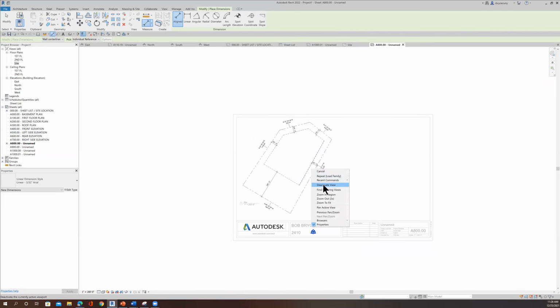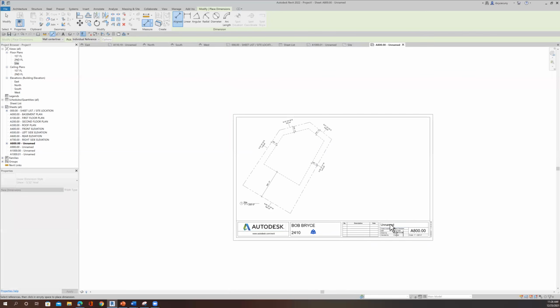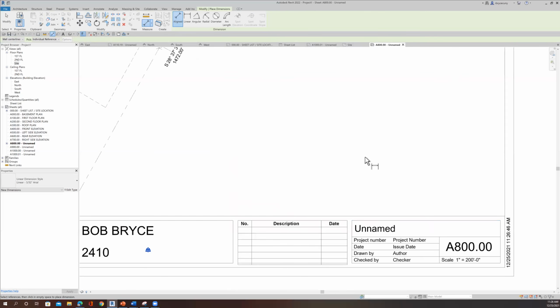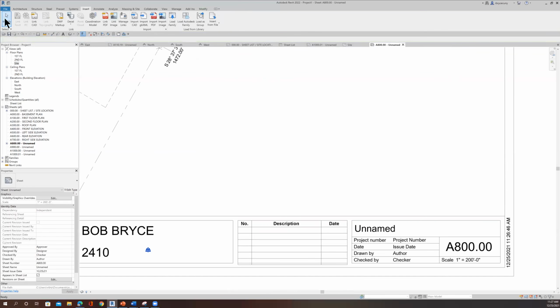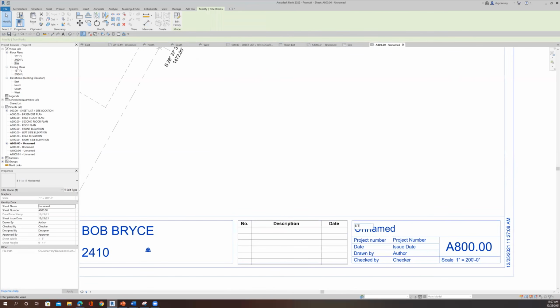So right click, deactivate the view. Let's call it, we'll rename it right here. Let's get in here and rename it. Click on it. Whoops, see that little icon next to my mouse cursor. You can see it. And what that tells me is that I'm already in a command. I'm telling Revit to do something, and that icon is telling me that I'm telling Revit to dimension. So I'll come up here and click this modify tab, and that clears it out. So now I'm not in a command, and I will double click on there and just say site plan.